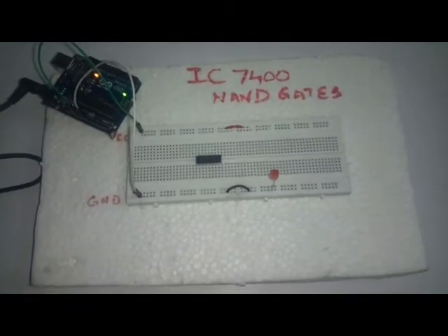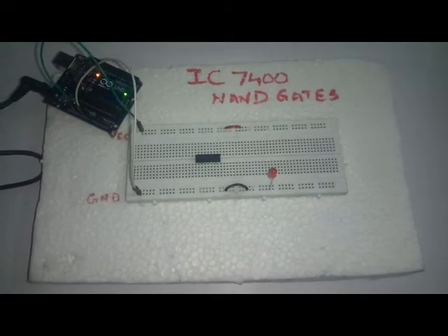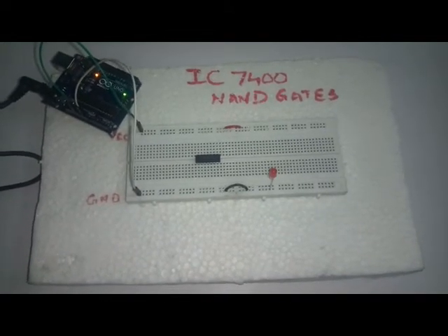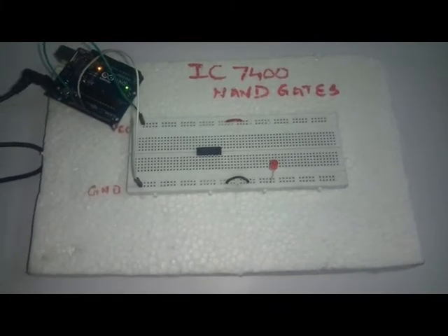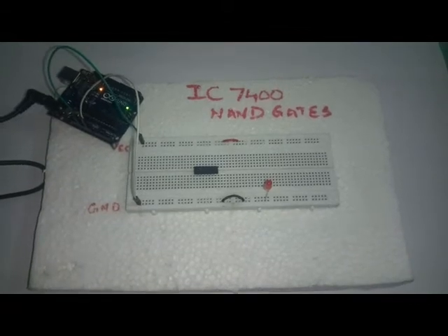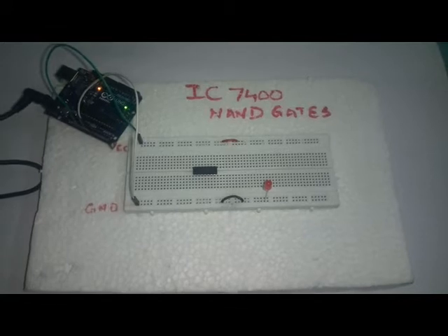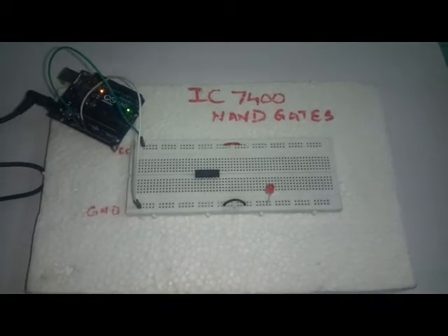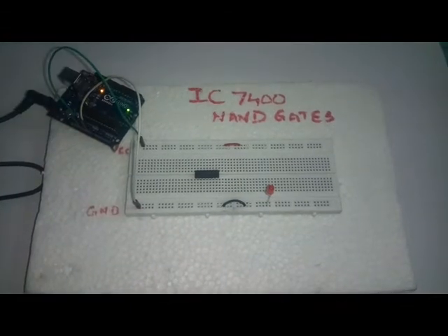Next we have to give the input supply to the IC. But you all have a doubt that NAND gate is a 2-input IC while the NOT gate is a single input IC. How can we convert a 2-input IC to a single input IC? So the answer for this can be explained using the logic circuit diagram of both NOT gate and the NAND gate.